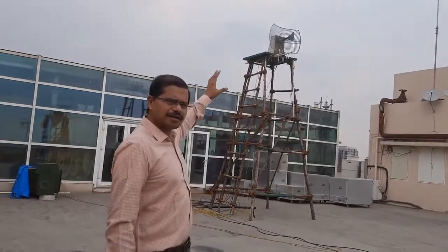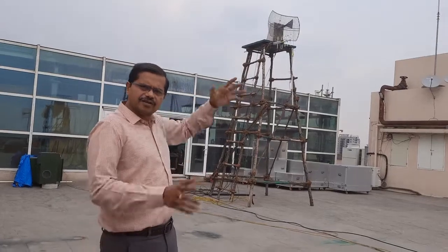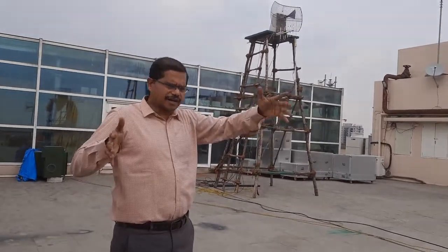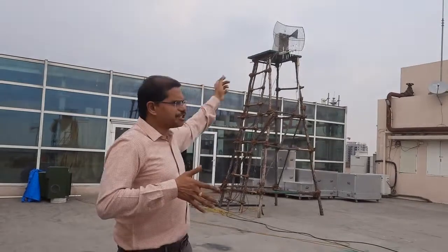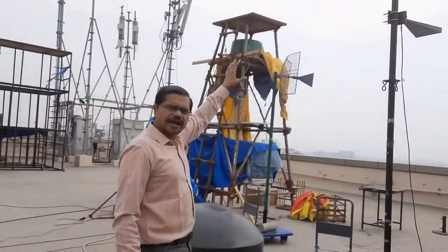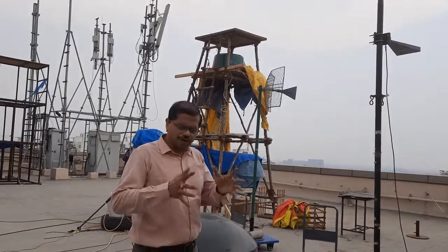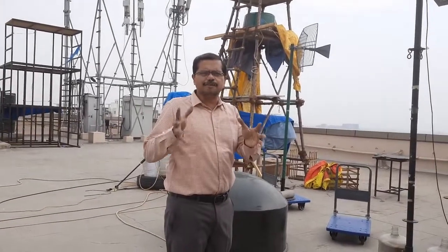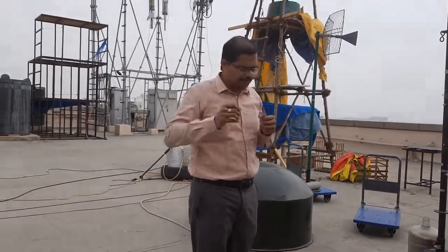We have a setup here which is capable of generating a narrow beam signal over wide frequency ranges, from 100 megahertz up to C band, up to 12 gigahertz, by which we position the antenna array that we want to characterize on the servo systems here, and we calibrate the systems. Then the calibrated data we use in the software for giving precise detections, direction of arrival, and location of the signals.